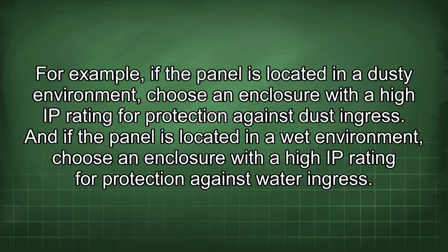For example, if the panel is located in a dusty environment, choose an enclosure with a high IP rating for protection against dust ingress. And if the panel is located in a wet environment, choose an enclosure with a high IP rating for protection against water ingress.